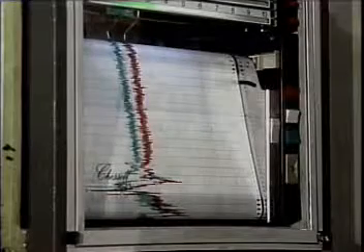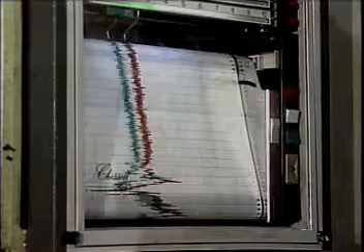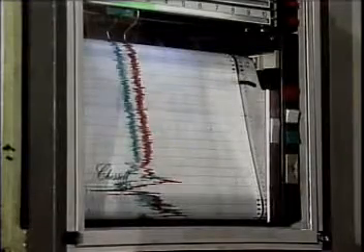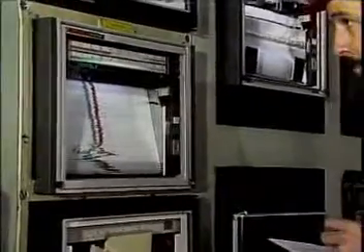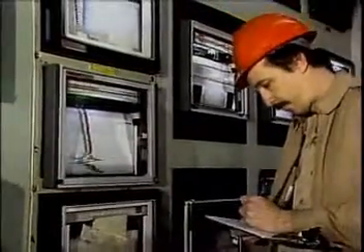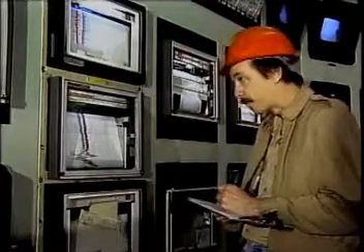Most boilers have an instrument that measures the level of the excess oxygen near the boiler outlet to the stack. Part of a boiler operator's job is to monitor the readout from this instrument and adjust the airflow when necessary to make sure that the excess oxygen level stays within the acceptable range for the plant.